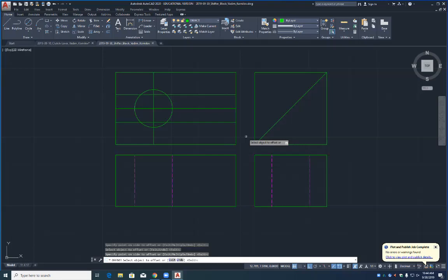Okay, so basically, the width of that slot has one tolerance, doesn't it? One and only one tolerance, the actual width of the slot, right? And let's talk about that a little bit. How wide is it? 1 inch wide. Give or take, it can vary that way, right? But it has one tolerance, doesn't it? Once it's printed, we basically don't need to put 0.5 twice.